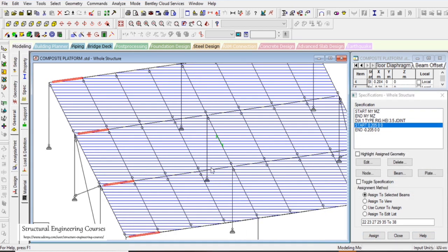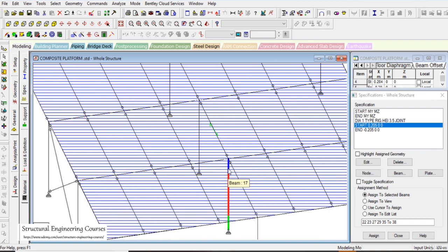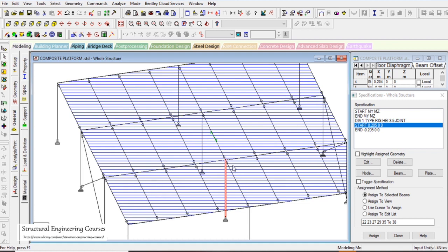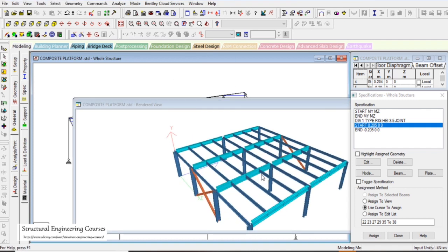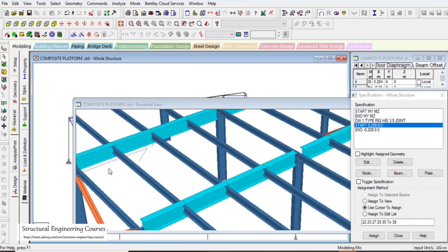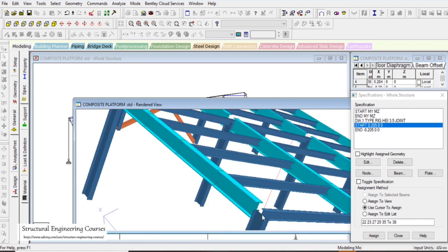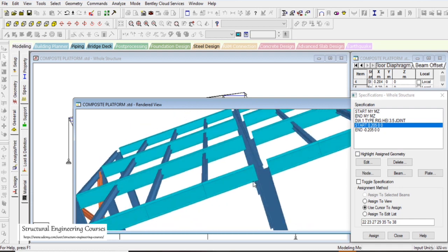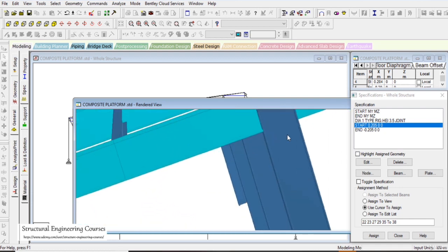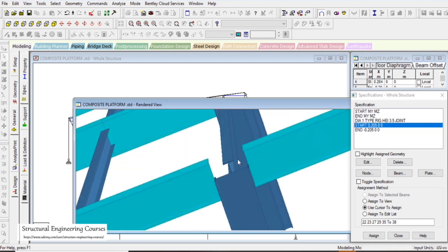So now we have done the correction for the beams, but after that we do need to do the correction along for this column location also. So let us check that whatever we have done is correct or not. So here we can see that for columns beam junction everything is okay, except this particular problem here, that the column is not going up to the top here.